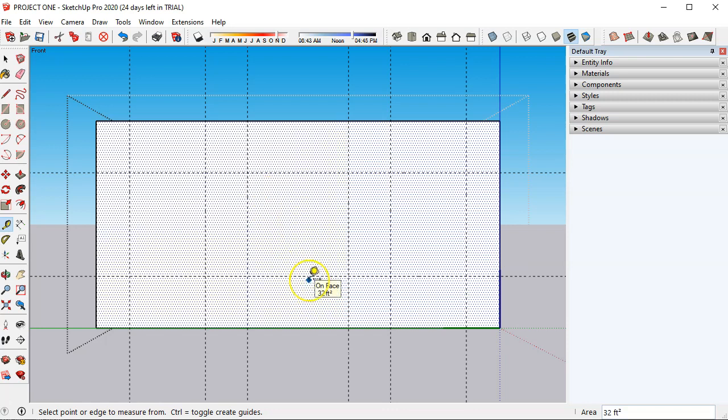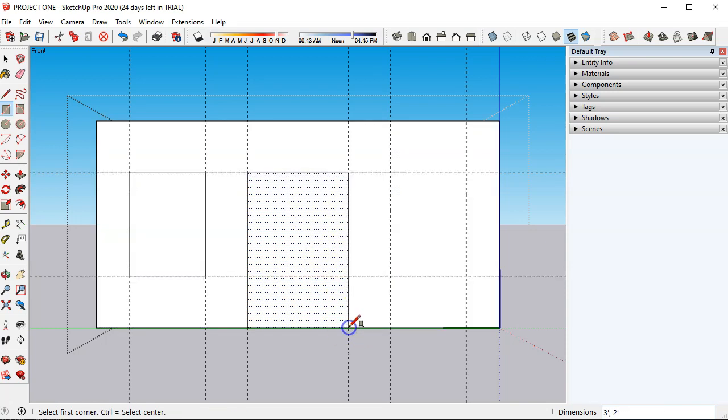You don't have to draw the X, but you do have to draw the perimeter of the opening. So with the rectangle command, you can just start, make sure it says intersection, pick there to there, intersection. For the door, pick there. You're going to come all the way down to the bottom, pick there, and pick there and there for the other window. All right.